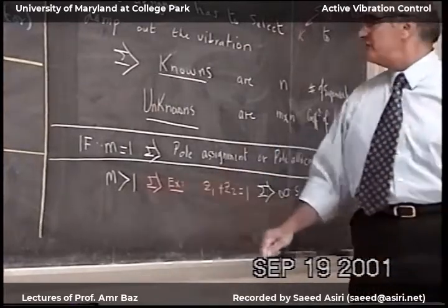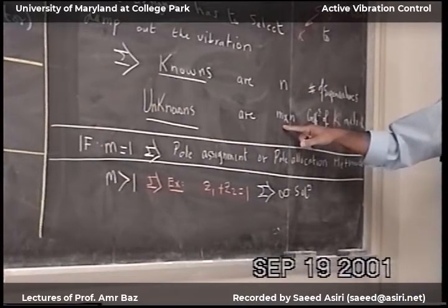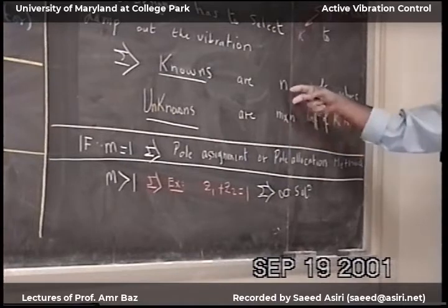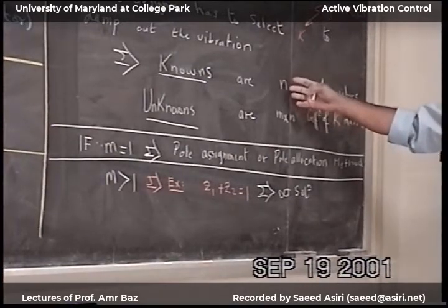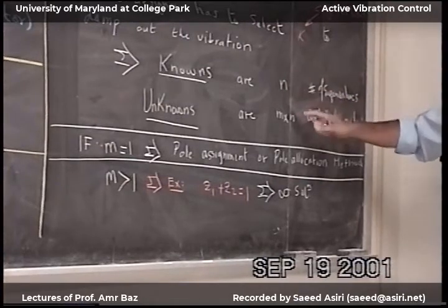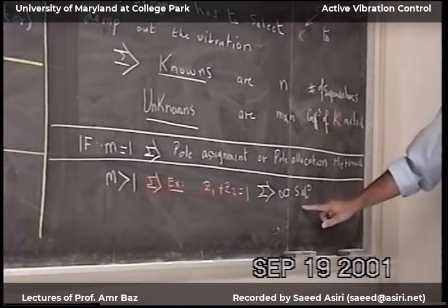If I have more equations than unknowns, I have a statistical problem. We have many test problems and we want to curve fit them with one parameter, for example, the stiffness of a spring. So we tension it with one force and measure the deflection. I have many data and one parameter, which is the stiffness, so I can curve fit it and get the stiffness. Our problem is different. We have a small number of equations and many unknowns. So this is a design problem.